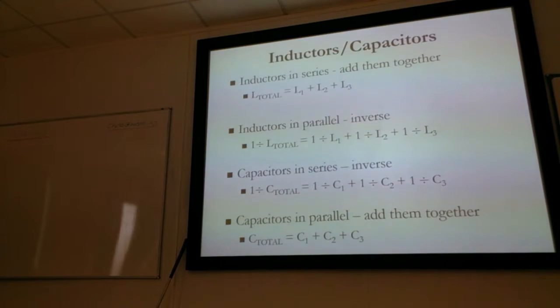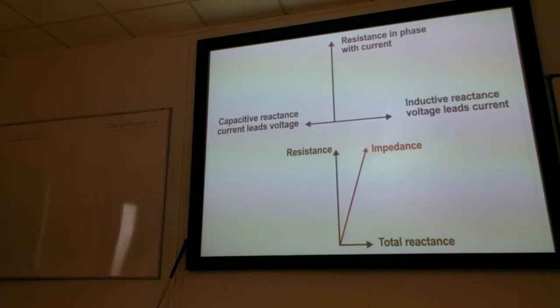Again, so what? Why do I even care? Well, I'm bothered because if I'm in a circuit that was purely resistive, that would be my amount of power that I'm producing or using. But capacitive reactance gives me a force this way. Inductive reactance gives me a force that way. Now, if I've got both capacitive and inductive reactance in a circuit, the capacitive reactance cancels out part of the inductive reactance and gives us the picture at the bottom. So it's a vector sum. The total reactance is that side of the line of resistance, and the total reaction between them is impedance.